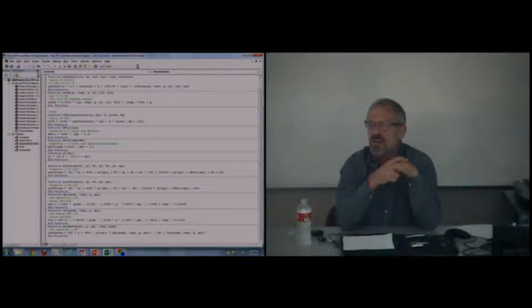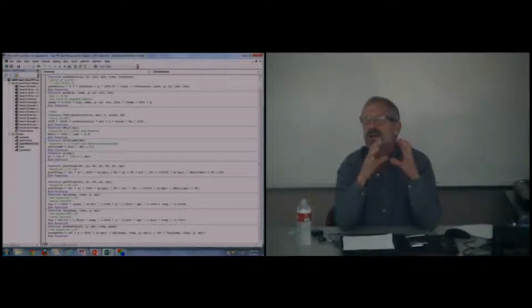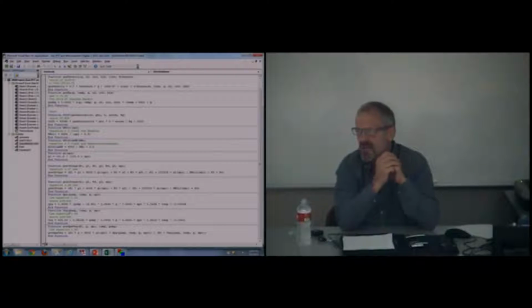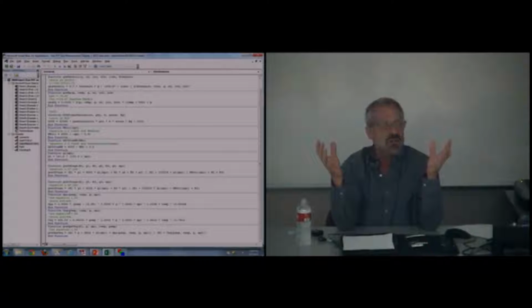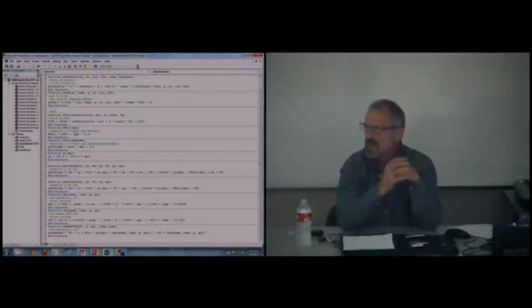And then we looked at it if we use correlations with the information we generally have when we're in the oil field, which is the pressure and temperature of the first stage separator, the API gravity of the stock tank liquid, and the gravity of the gas leaving the primary separator. In the general situation, those are the only two things sold, and so those are the only two things measured: the gas gravity and the oil API gravity. Both of those enter into the calculation of what the purchaser will pay for that fluid, gas or oil.